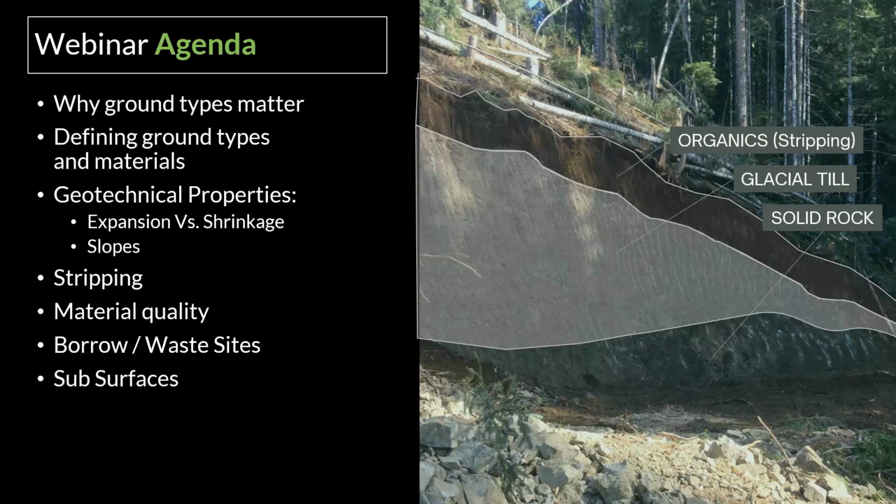We're also going to talk a little bit about stripping, the concept of material quality, leveraging borrow and waste sites, and finally looking at and implementing subsurfaces. That's our agenda for today. If I leave you with one thing, leveraging ground types adds a huge amount of realism to your project and makes it much closer to reality when it comes to your cut and fills.